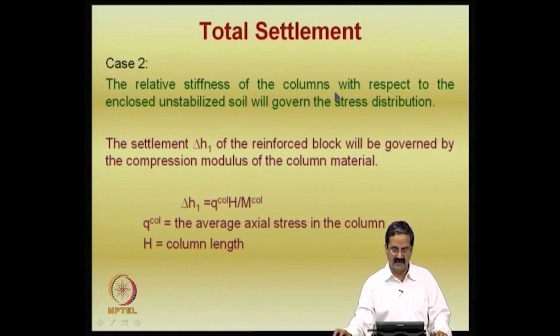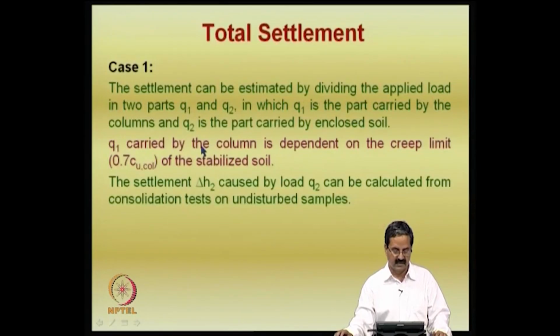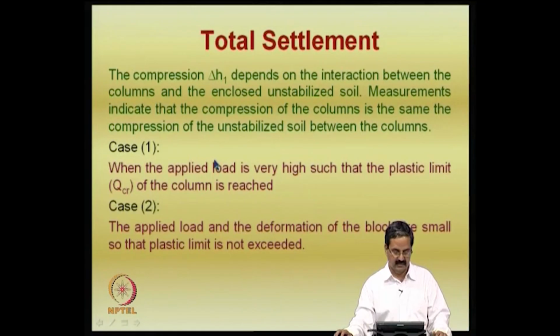Case 2 is that the relative stiffness of the columns with respect to the enclosed unstabilized soil will govern the stress distribution. Let me go back to the first case, when the load is applied such that the plastic limit of the soil is reached. The second case is when the loads are small.